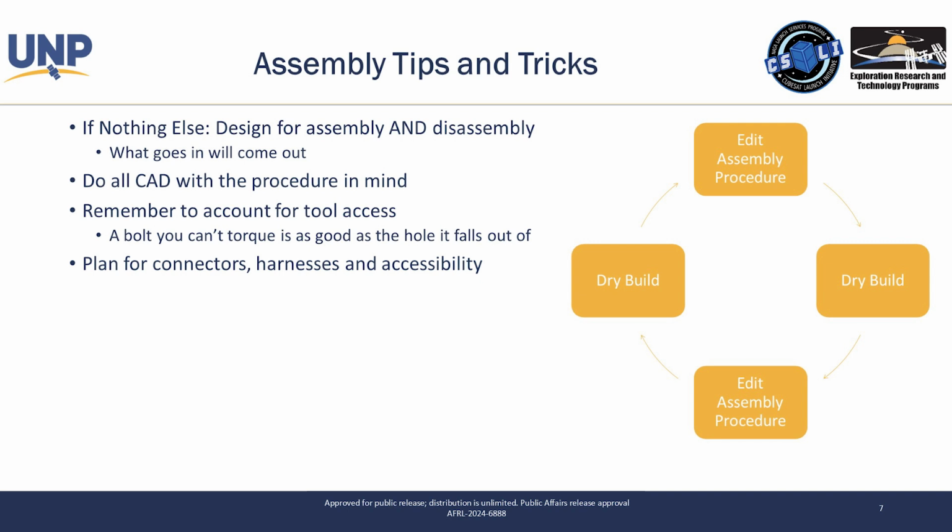Because if you cannot torque that bolt, it will fall out, it will cause chaos, and it will break everything. And so that is something that we very commonly miss, and is excellent to practice in the dry build before it really matters, before it's going into the extraordinarily violent launch environment and everything breaks and your mission fails.